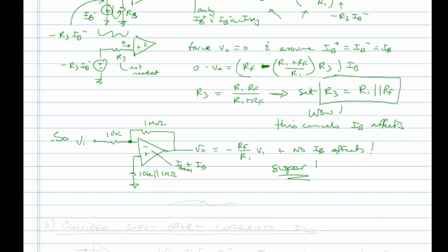But sometimes, because a real op-amp is going to have not only the bias current effects, the offset voltage effects, and then the offset current effects, trying to zero one out completely may not be merited, because long before you totally zero it out, one of the other non-perfections in your op-amp will start dominating, and so there's a point of diminishing return. So maybe just putting 10K here would be good enough. I don't know. We'd have to actually work through an example.